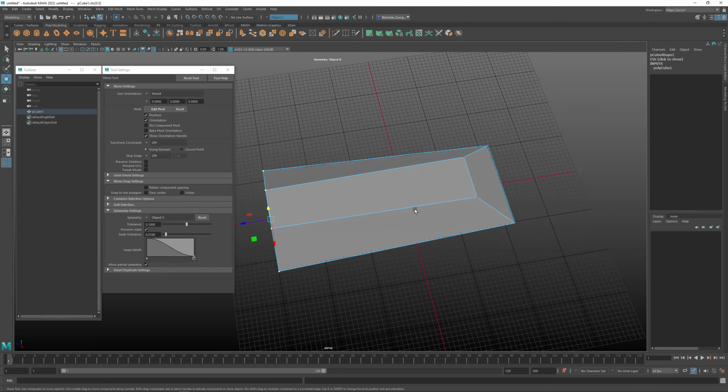Like, so we've got all these verts, and I'm going to hold down X, and I'm going to snap to the grid this way. And so you can see now everything's nice and snapped up. Everything's going to be precise whenever we want to manipulate this. Now I think from the side view I've got to go, and you can see there's an angle on this, so I'd have to hold down X and kind of snap this way.